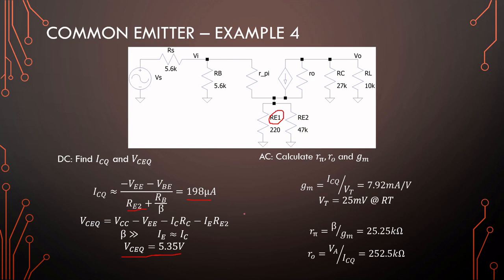Design equations are used because we want VCE to be at 5 volts. But don't ever assume, when you're analyzing an amplifier, that the designer was using the design rules. Okay, design rules are based upon what's good, but in a certain application, designing an amplifier a tiny bit different would have been much better. So don't make that assumption when dealing with analysis problems.